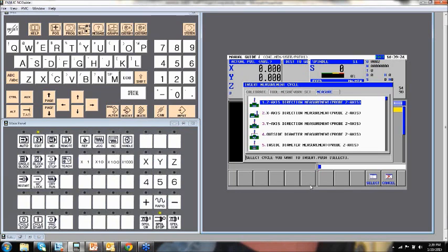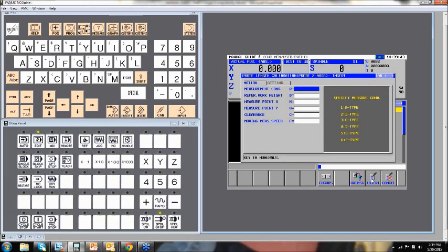And again, it could be something created on a CAM system, and you could put this probe cycle within that. So it's very flexible from that standpoint. But again, we have the same four. And the thing about this is, if we look at the probe length calibration, it's a little different. But when you measure it manually, it's still going to put those values in the right condition. But again, we tell it the measurement condition, the reference work height, and where you are in X and Y.